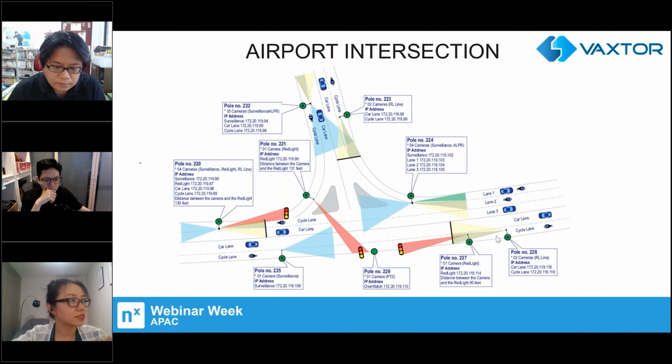For this red light violation solution, basically the objective is very simple. We use the camera to detect red light cross violation, that kind of case. But the key information is that unlike a lot of traditional designs, people always have to link the so-called red light camera or ALPR camera to the traffic light relay controller. And in order to detect whether there's a vehicle overrunning this particular line, people still have to excavate the road and embed the loop detector.